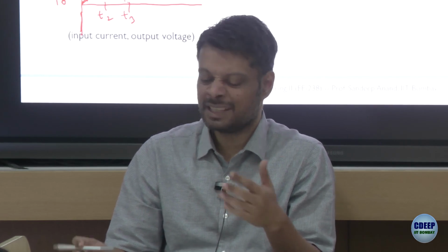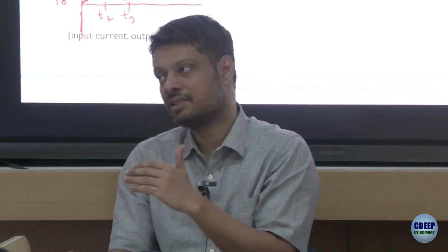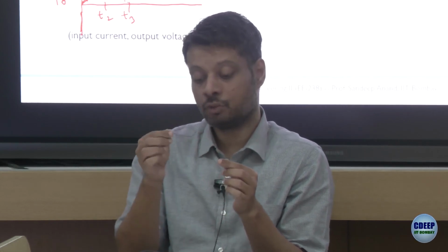Okay. So the equation is fine: V naught minus I naught R is equal to L di naught by dt. So immediately after T2, assuming there is a large inductor, the current remains the same. So I naught R remains the same, which was there just at T2, but the voltage has reduced, right?